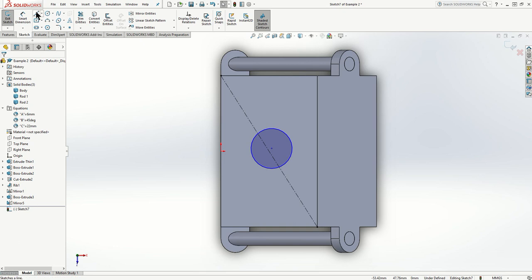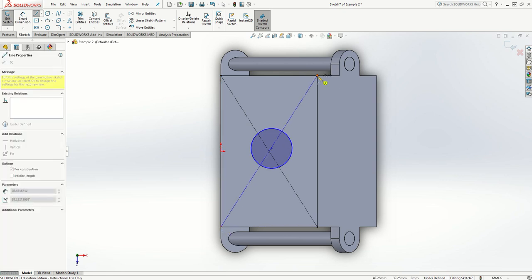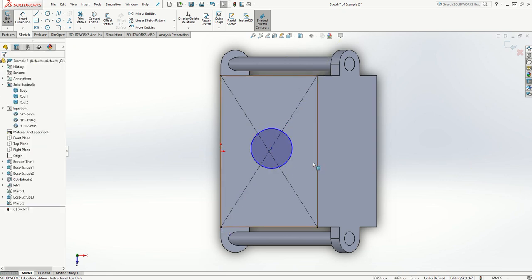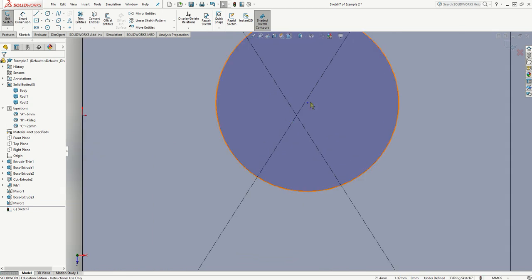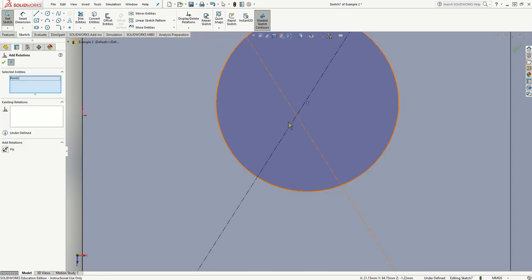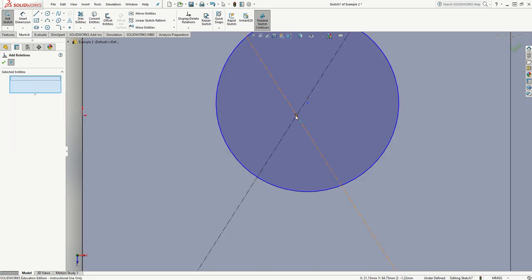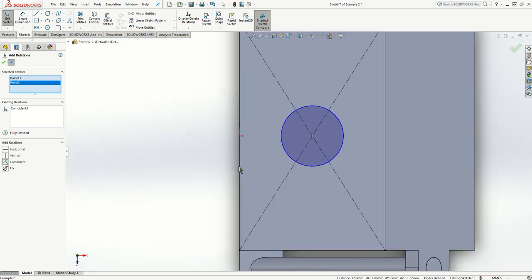If you want to feel more confident in the circle you're choosing, do another line. Construction from here to here. And now you know for sure where the center is. You're going to grab the origin of the circle, press Control, and grab add relation from this point here, which is not working right now. Let's get rid of this first. Let's see if it lets me grab it. This one here first. Get rid of the line here. And this point here. And we're going to make it so it's coincident. And now it's in the middle.